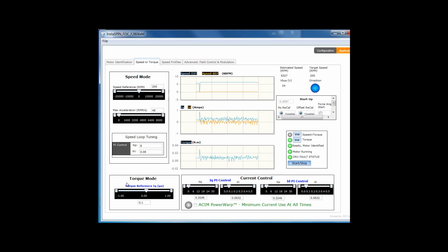So this is one way that you can get more speed out of your motor, by really using the available voltage bus that's there. You probably can't hear it, but the sound when you move into the trapezoidal does change significantly from a sine wave. It does become noisier, and that's something you have to think about as a trade-off in your system.